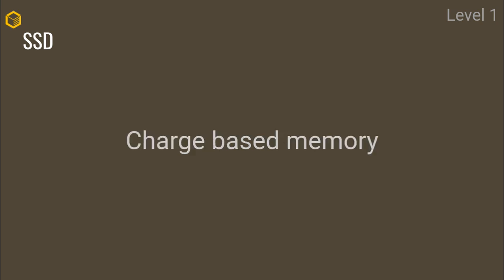SSDs, which is the purpose of this talk, but actually flash memory, is also called solid state drives. It is charge-based memory. So charge-based memory means that the memory value is associated with a certain amount of charge on the bit cell. We'll go into this more in detail later, but as you might recall, if you were there on a previous memory talk, we have another type of charge-based memory that we use in our daily systems, which are the DRAM memory cells.